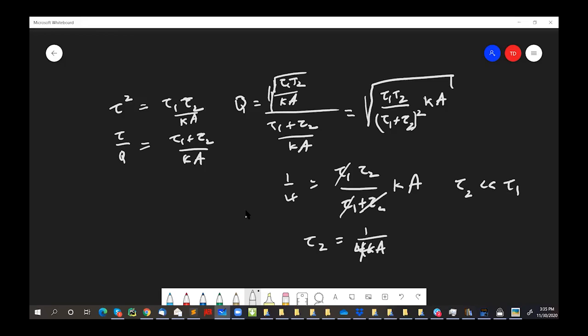So it has to be really fast. Like suppose the loop gain is 100 going around. That means the amplifier has to be 400 times faster than the input time constant. That's a lot faster, right? And the higher you make the gain of the amplifier, the more it has to be faster. So that's one interesting thing you can observe. And if you do that, though, you should get a stable response to the final value. No ringing.